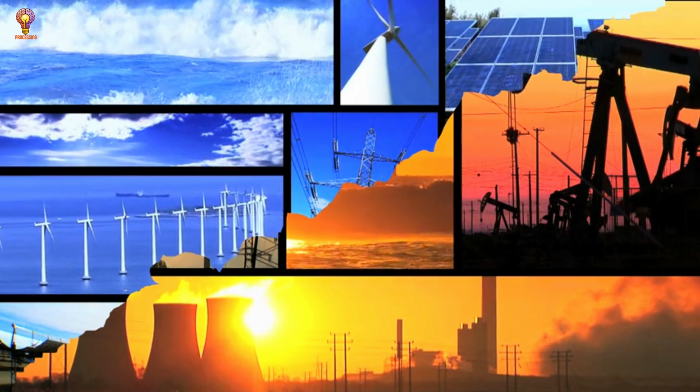Cooling and condensation. The steam, after passing through the turbine, enters a condenser, where it is cooled down using water from cooling towers. It turns back into water and is recirculated into the boiler. Flue gas treatment and emission control. Electrostatic precipitators or bag filters remove particulate matter from exhaust gases.